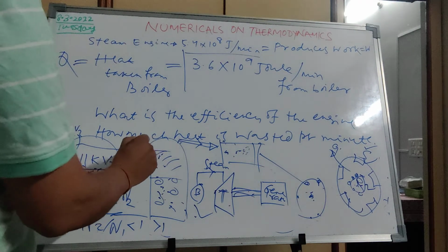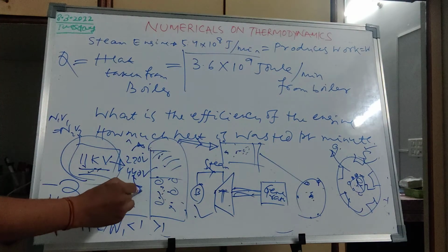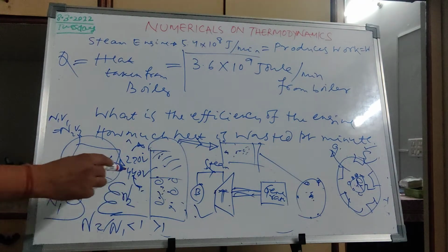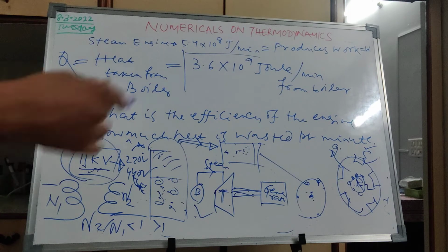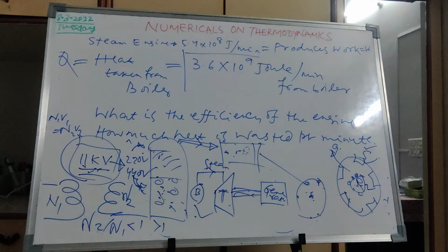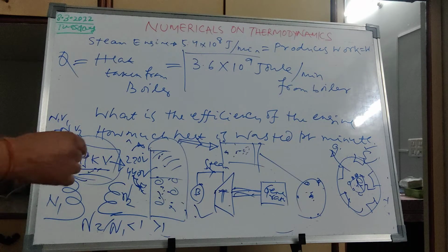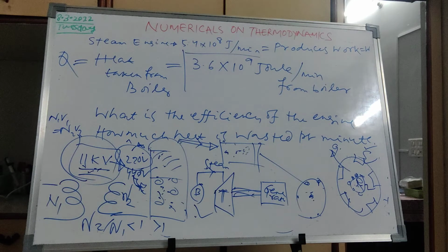The 220 volt is single phase, and 440 volt is three phase. If you want to drive a 10 HP induction motor, you need 440 volt for industrial purposes. For domestic use, at maximum you need a fridge or a small 1 HP motor, so we can use 220 volt for that.